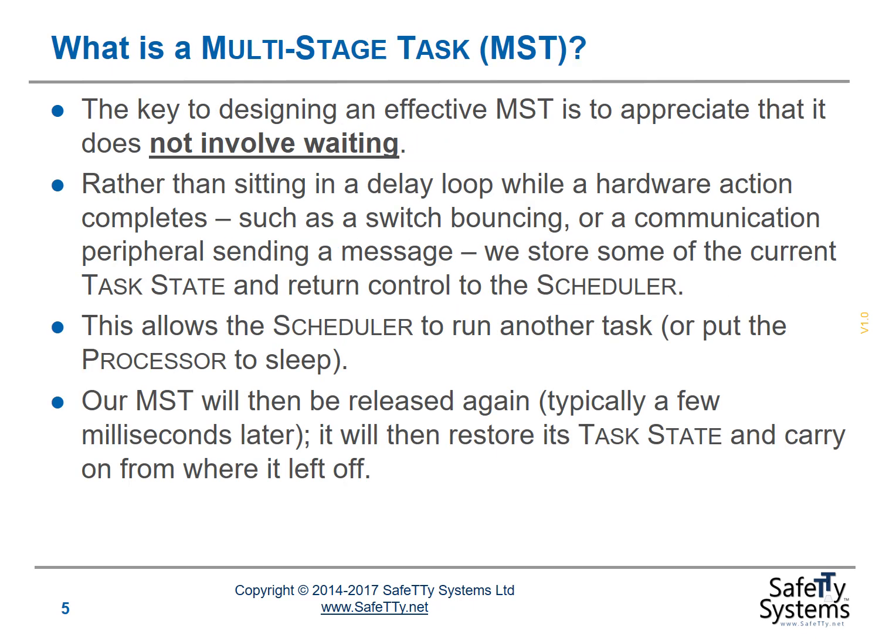So what do we mean by a multi-stage task? The key to designing such a task is to appreciate that it does not involve waiting. If you've got a delay loop in your task, you're probably doing something wrong. So rather than sitting in a delay loop while a hardware action completes, for example, while we wait for a switch to stop bouncing or we wait for a UART to send some characters, what we do instead is we store the current task state.